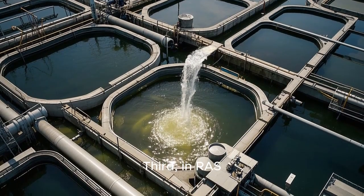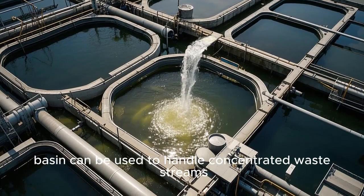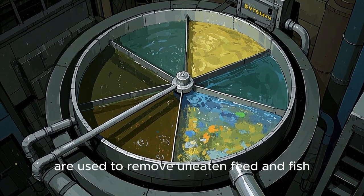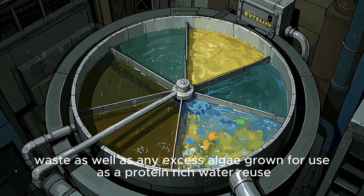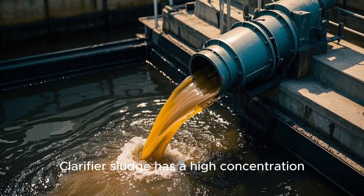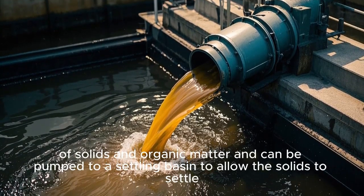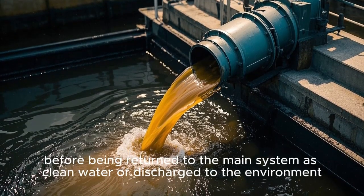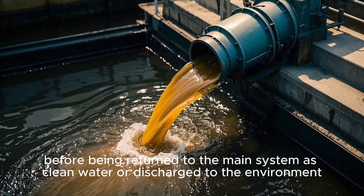Third, in RAS, there are several points where a settling basin can be used to handle concentrated waste streams. Clarifiers, for example, are used to remove uneaten feed and fish waste, as well as any excess algae grown for use as a protein-rich water reuse. Clarifier sludge has a high concentration of solids and organic matter, and can be pumped to a settling basin to allow the solids to settle before being returned to the main system as clean water or discharged to the environment.